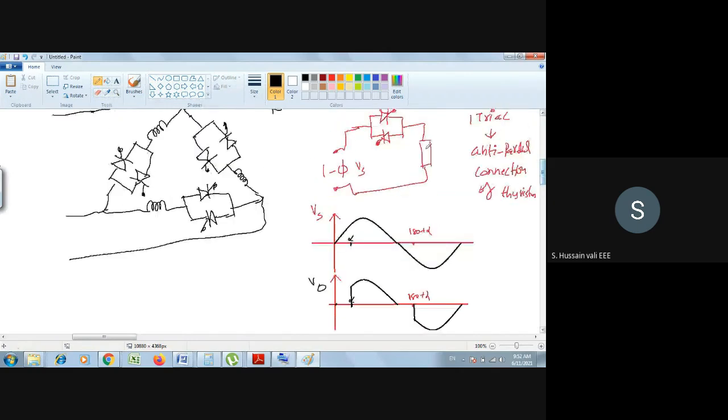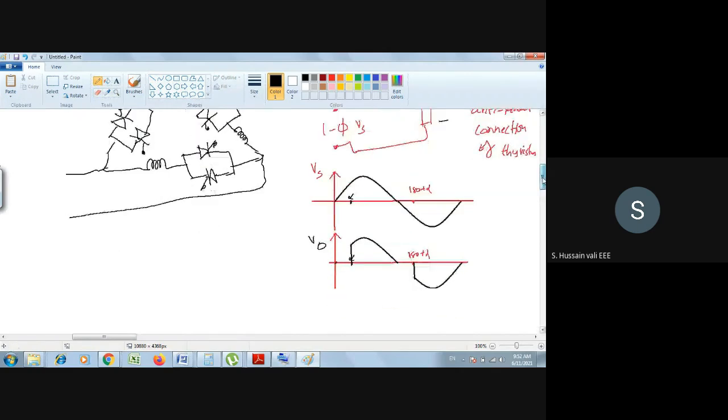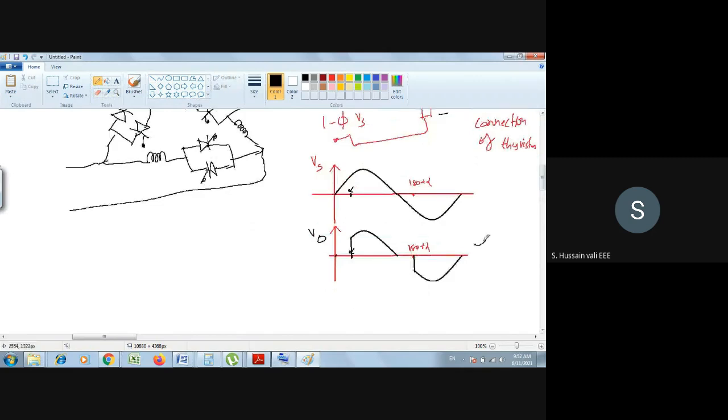By knowing the RMS value of this waveform, which we might have derived already in the case of the Fourier transform, you see that the RMS value is a function of alpha. As it is a function of alpha, if alpha varies, the RMS output voltage also varies. It means the stator voltage varies. So this is the logic behind these AC voltage controllers.